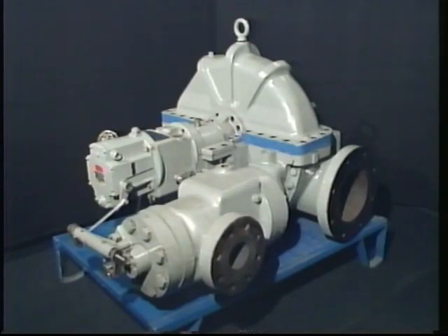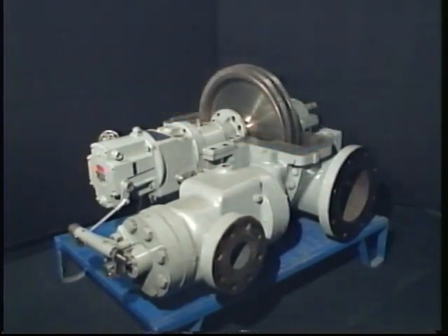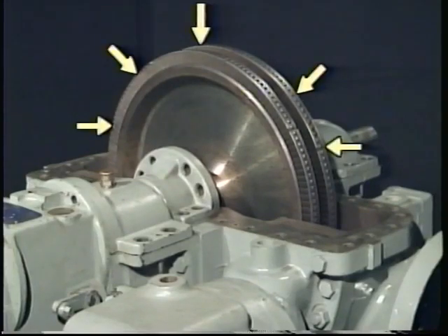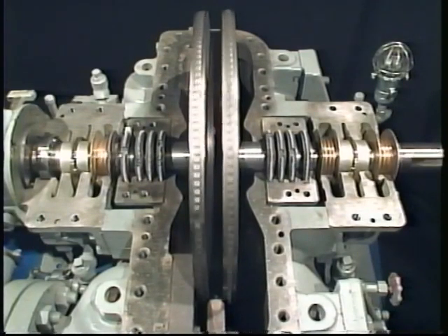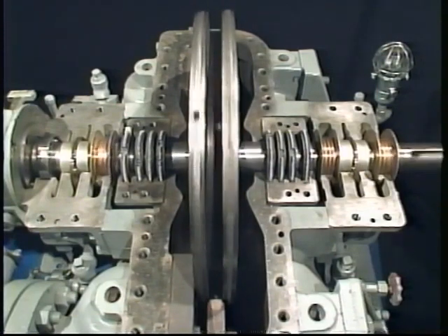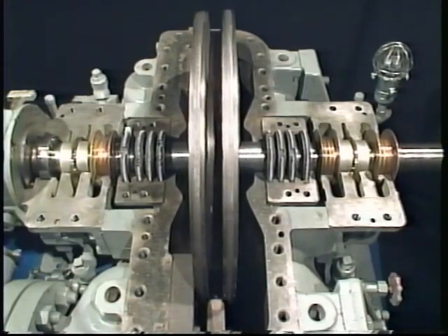The blades used in steam turbines are a little different from the simple fan blades we just saw. Let's take a look at some typical turbine blades and see how they do their job. Generally, turbines use a series of fixed and moving blades to make the most effective use of the steam's energy and cause rotary motion. The blades shown here are designed for what is called impulse movement. Basically, impulse means that the high-velocity steam pushes on the blades and causes the blades and the shaft they're mounted on to rotate. We'll take a closer look at how impulse movement works in a moment.